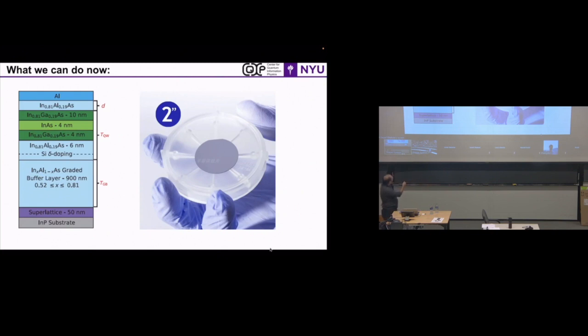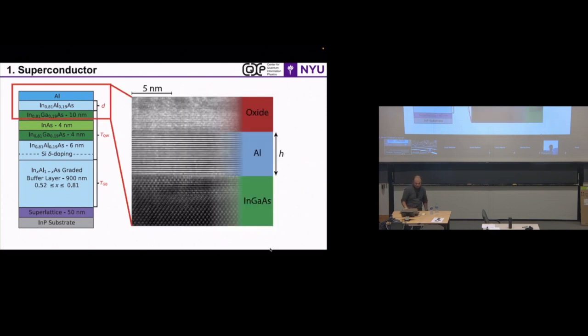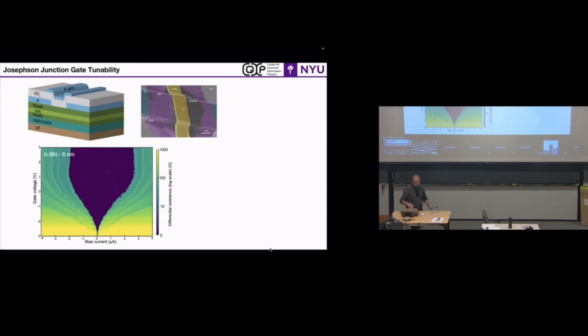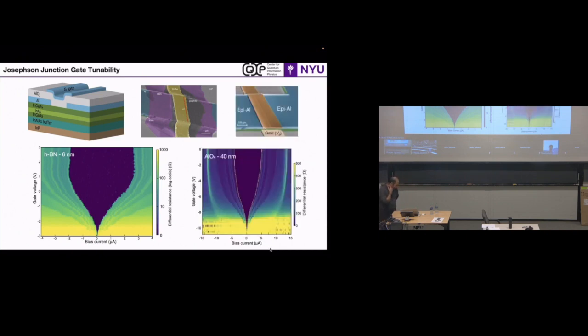Because of that, we can put it on indium arsenide, but we lower the Schottky barrier to 0.81. So we don't have a rush of electrons at the surface. We just get the right number of electrons that we want. Then we can put this epitaxial aluminum on top of the InGaAs. So this is the structure that we will use throughout the talk. And we grow one a day now, for various collaborators and various projects. So I want to show you this as the variety of what you can do.